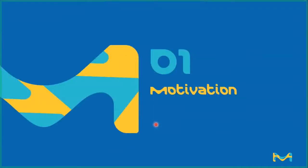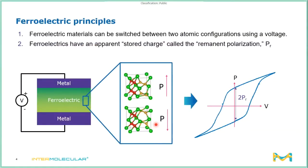So starting with the motivation, what is making people so excited about ferroelectric hafnium oxide? First, let's start by talking about what a ferroelectric is. So here you can see a ferroelectric material that we've sandwiched in between two metal electrodes to make a capacitor structure. When we apply an electric field across this ferroelectric material, we can actually switch it between two different states. One state where the atoms are organized as we can see here, and the other one where the atoms in yellow actually move up towards the top of the crystal lattice.